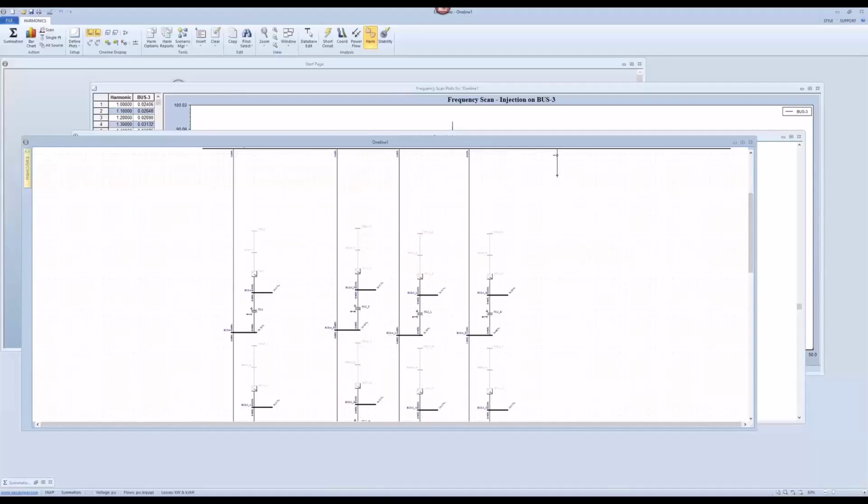We said that at the beginning, right? Next question: the manufacturer provides harmonics for each phase. Do you use the maximum? Use the maximum. Sometimes we use the positive sequence average, but I use maximum, and I recommend using maximum to be conservative, right?